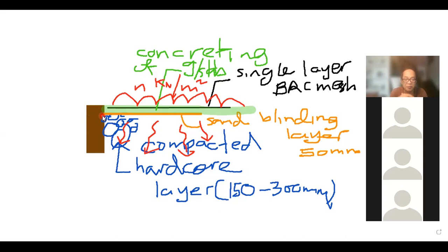So if we have a good soil, tanah yang bagus, we have an area of cutting, and the building is to be built on cut area, then we would safely say non-suspended ground slab would be a reasonable solution, and it is a very economical solution.